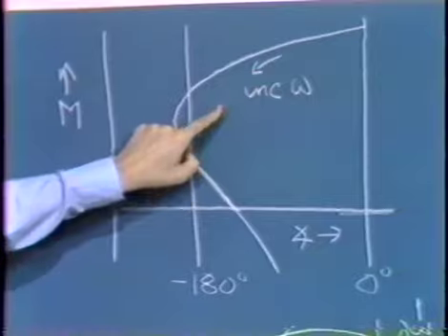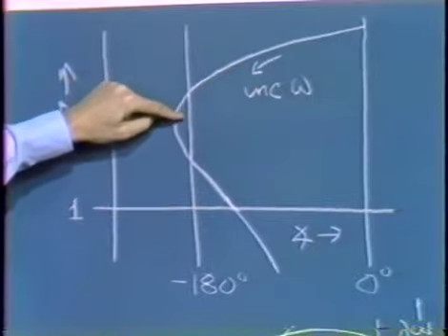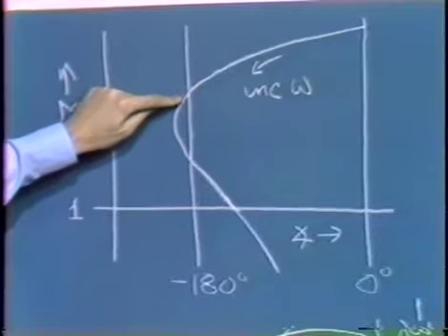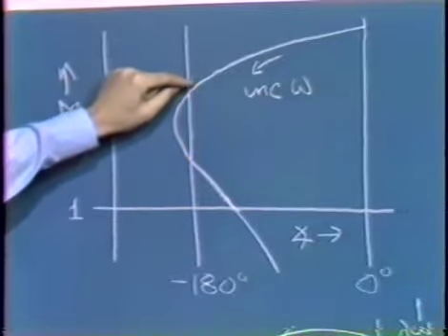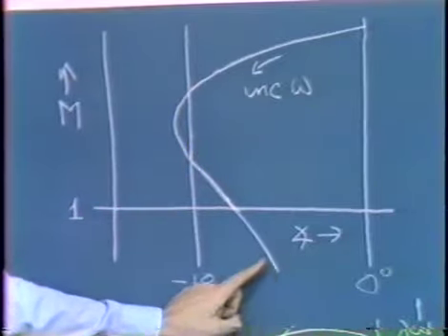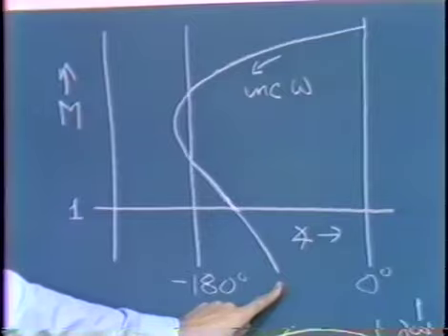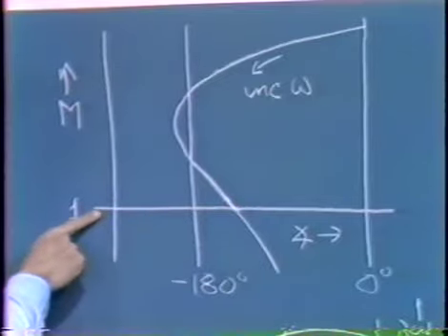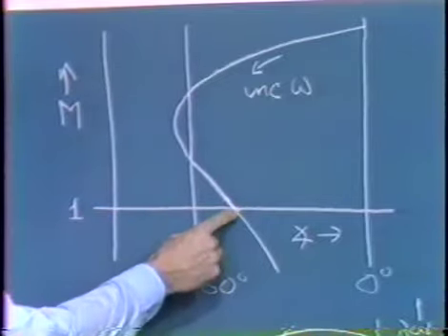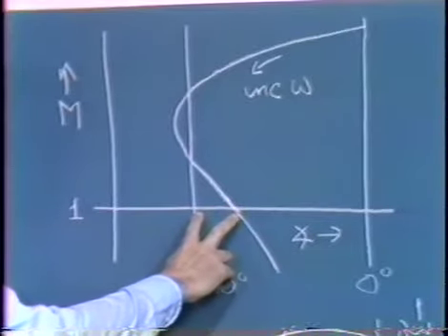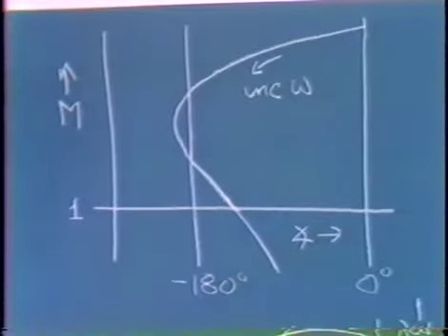As omega increases, the angle becomes progressively more negative, eventually drops below minus 180 degrees, remains more negative than minus 180 degrees over some range of frequencies, and then recovers, asymptotically approaching minus 90 degrees for very large values of omega. Again, we notice that since we go through the magnitude equals 1 point with the curve to the right of the minus 180 degree line, we have perfectly acceptable phase margin.